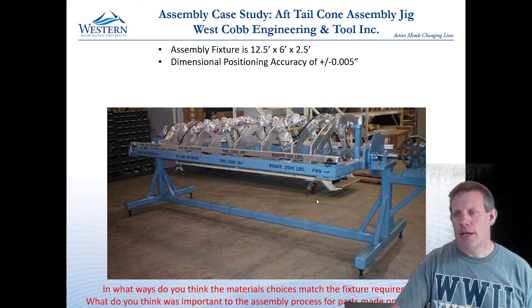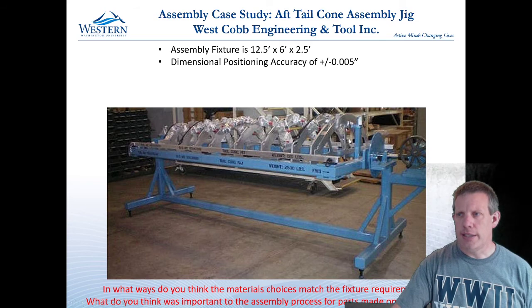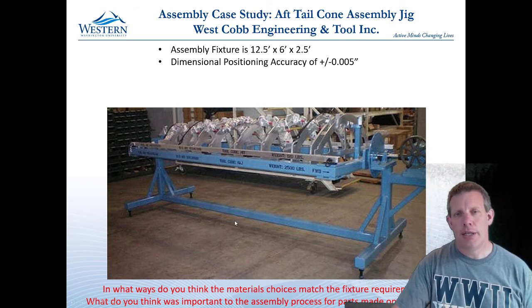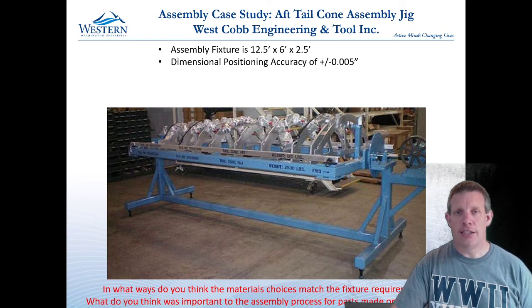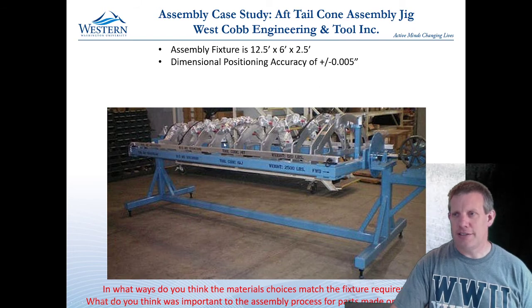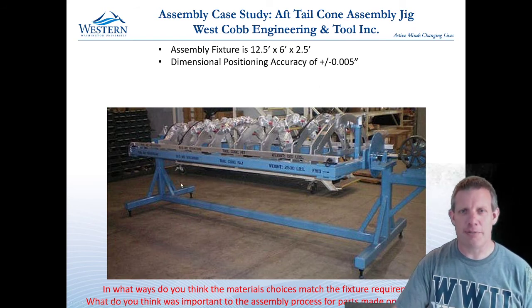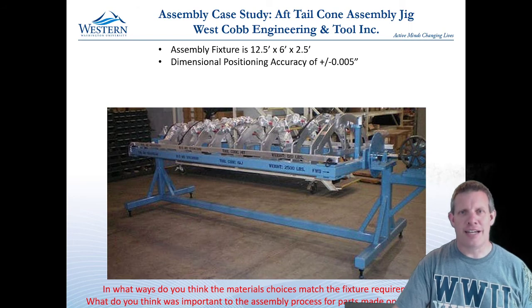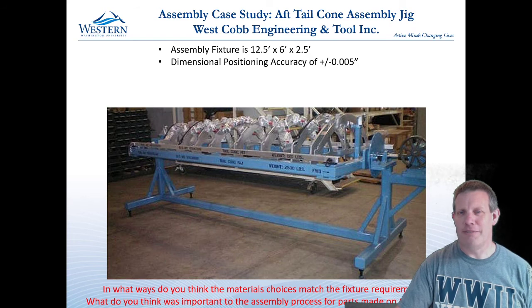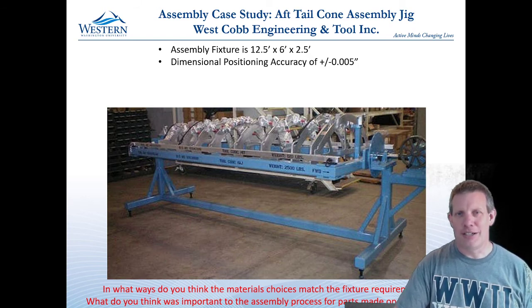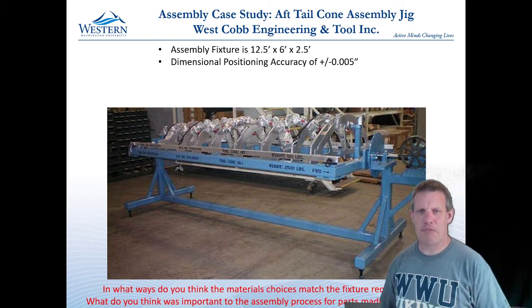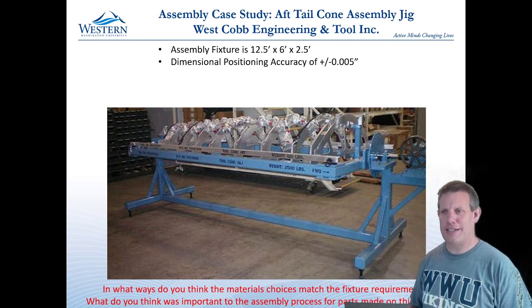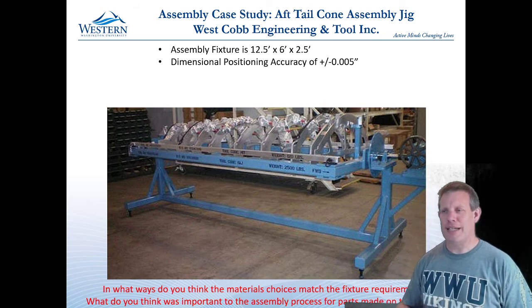Well, when I look at it, one of the things that I think is, look at the number of ribs that are on here and the number of clamps. It is clearly non-deterministic, right? We could approximate, it's an arc, but we could approximate it as a plane and say that it ought to contact in 3 points to be deterministic. Maybe if you want to say it's a plane plus you're preventing 1 or 2 other degrees of freedom because it's an arc, maybe you're getting to 4 or 5 points of contact if you're really pushing things, but that's all.